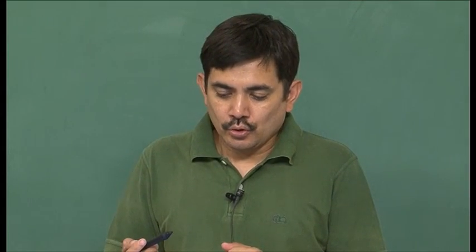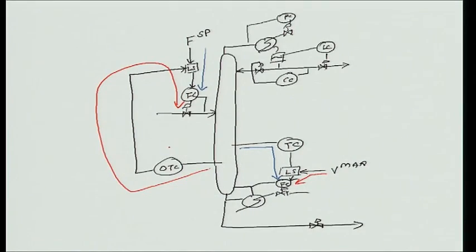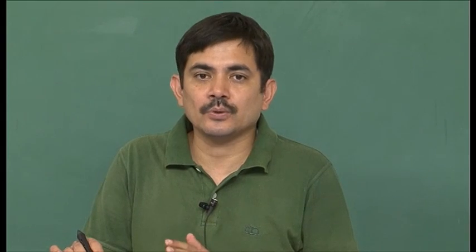Okay. So, the disadvantage of this scheme is the fact that SP2 must be less than SP1. Why does it have to be less than SP1? So that when temperature is being controlled by the boil up, when this loop is on, I do not want the override temperature control to be adjusting the feed. So, that will require that the set point for the override temperature controller be sufficiently away from SP1.